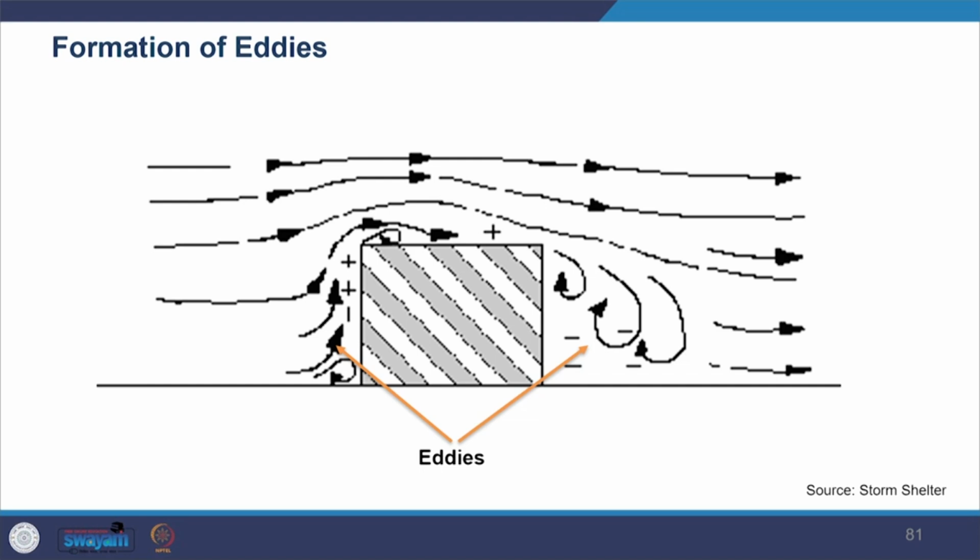So, you can see the impact, like how the wind really moves around the building, which causes the pollution to go down. Similar problems may occur if adjacent buildings or hills are within a certain distance, for example, 5 stack heights of the release point. In such cases, the buildings can influence the stack emissions, so there can be a change in the pattern. Therefore, it is important that the local context should be considered in the modeling. That is why you see how different things can change how the pollution travels.